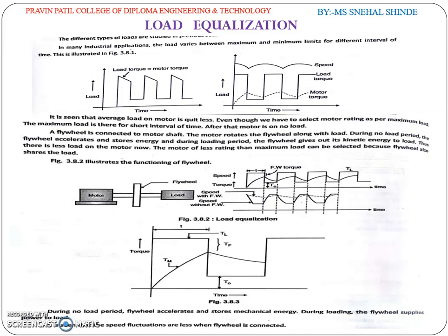During loading, the flywheel supplies power to the load, and the speed fluctuations are less when the flywheel is connected. So this is the method of load equalization.